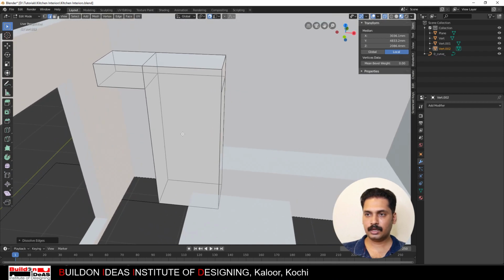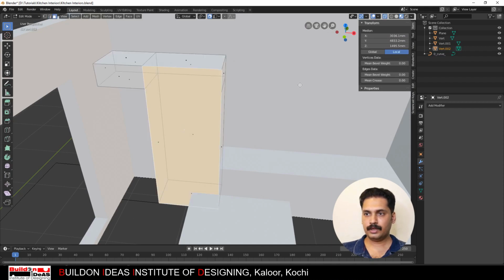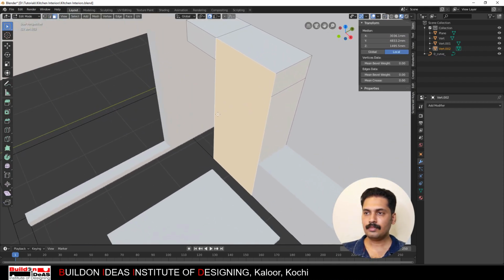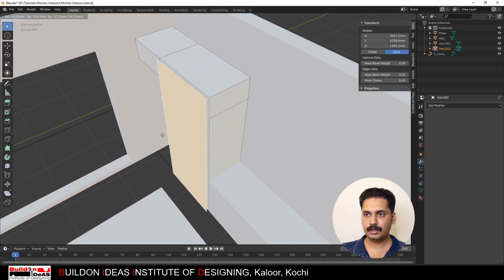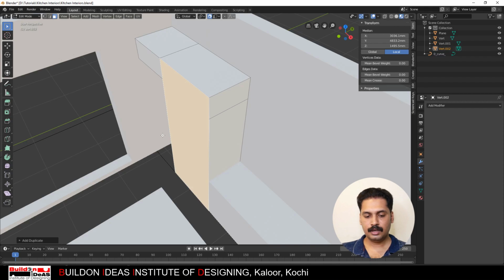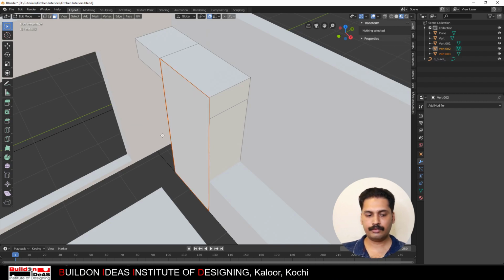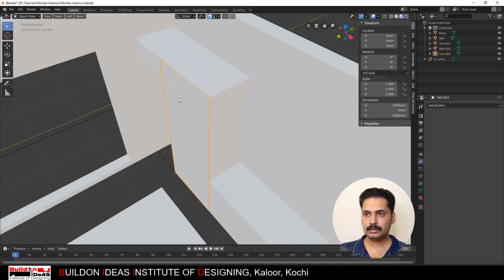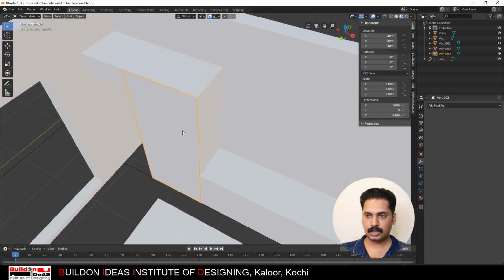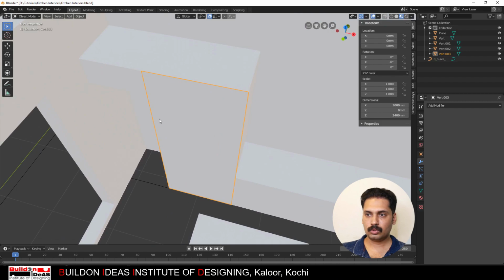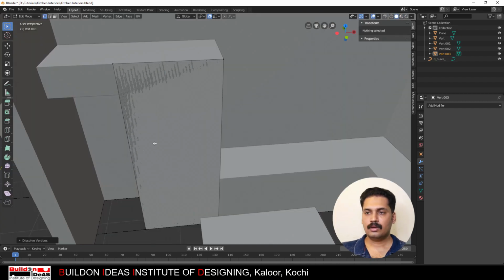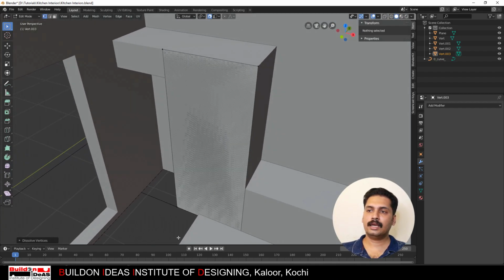So before that, I'll select this face. So this face is selected. I'm taking a copy of that by clicking Shift D, clicking Escape, and then clicking on P to separate that from the other model, so that object, and then I'm going to split it into two to get two portions. Okay, now selecting this face, I click on Control R.